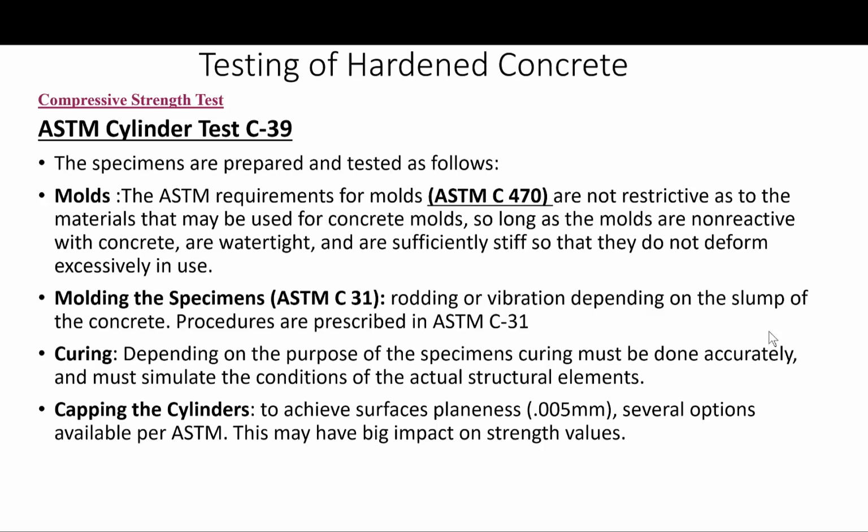Okay. This is in part because the top ends of these molds often take on a somewhat oval shape, and in part because some of the applied compactive effort, like the rod or vibration, goes into deforming the mold rather than just consolidating the concrete. Okay, so while the somewhat lower strengths obtained with the single-use molds are not of much importance for normal concretes, they can be significant for very high strength concretes, above 100 MPa.